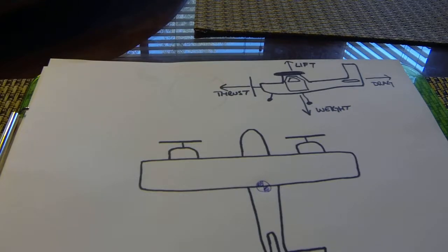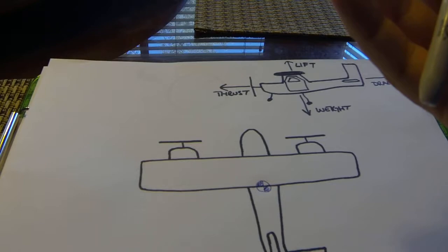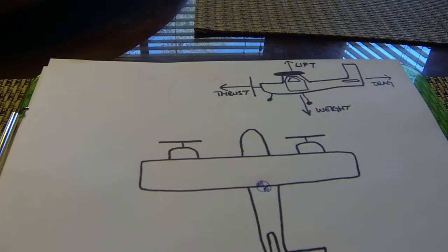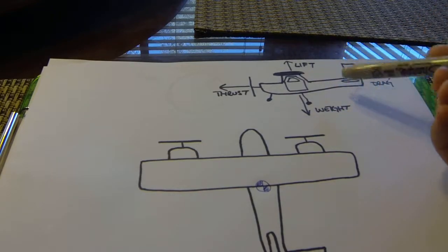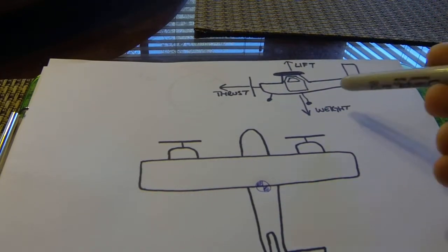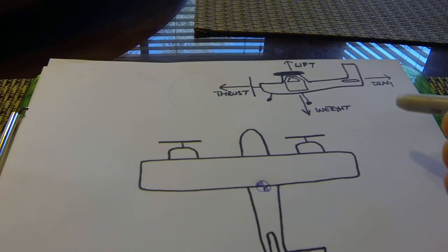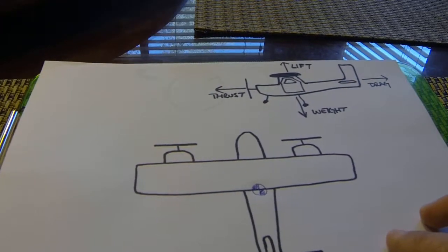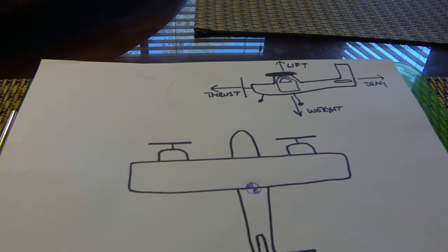Also, the airplane is having its most difficult performance; it's not performing as well as if it was really light. Now, as I mentioned, max weight can help us with VMC because a heavier airplane is developing more lift. Lift equals weight in the diagram here, so that can help us. However, performance-wise, it places more strain on the engines, and it will decrease our ability to maintain directional control.